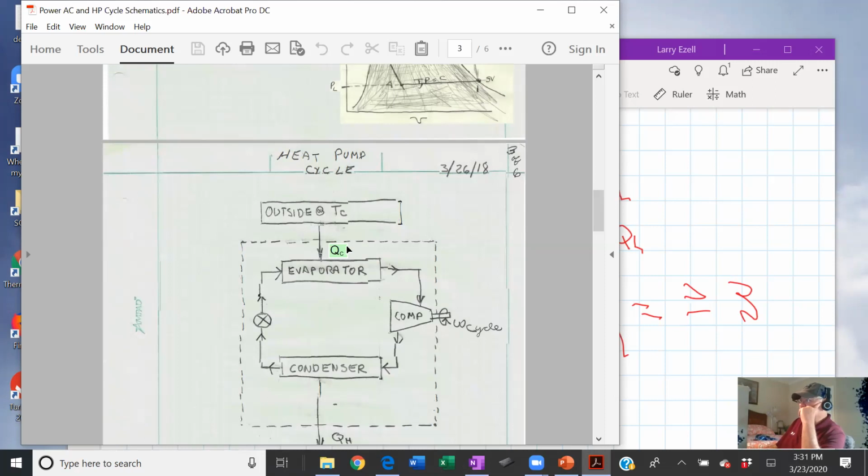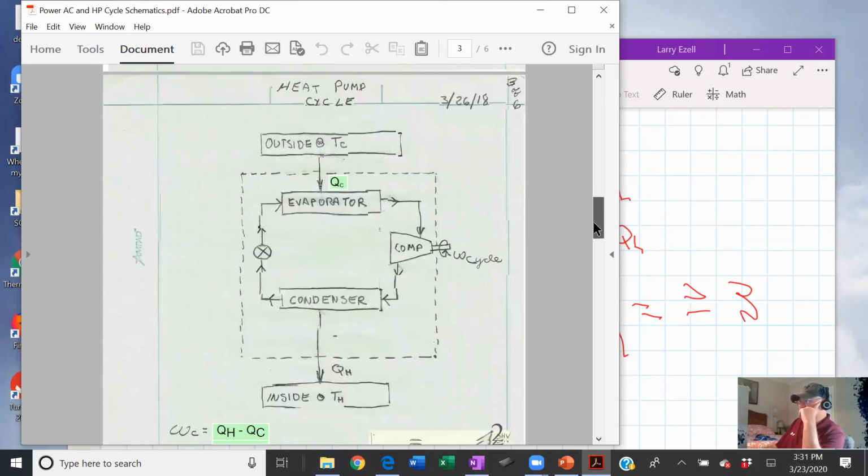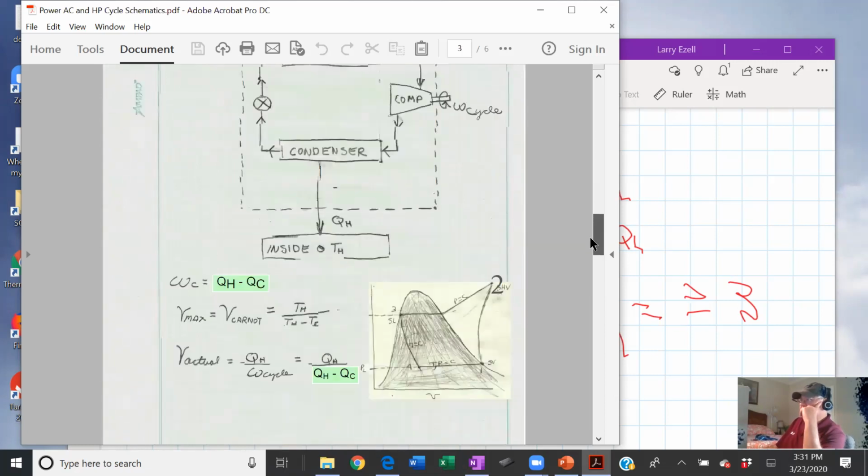And again, if the outside gets, say, 32 degrees or below, it's going to frost over the coils and make it really hard. You can get around that by not letting the air get to the coils. But what you can't get around is the minimum temperature you can get this refrigerant. It gets much below about 30 degrees, it just can't get any below. So that's a practical limitation. So just a little real world thing.